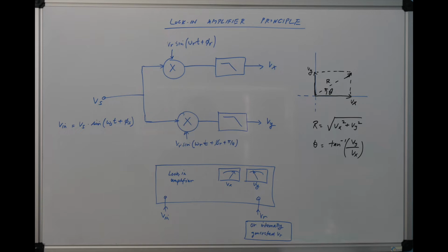We have basically extracted signal Vs out of a noisy environment which contains other signals. What this lock-in does is extract only the signal that is at the same frequency as the reference clock. Now we'll look at the case where the frequencies are different, and what implications it has on the output of the lock-in amplifier.